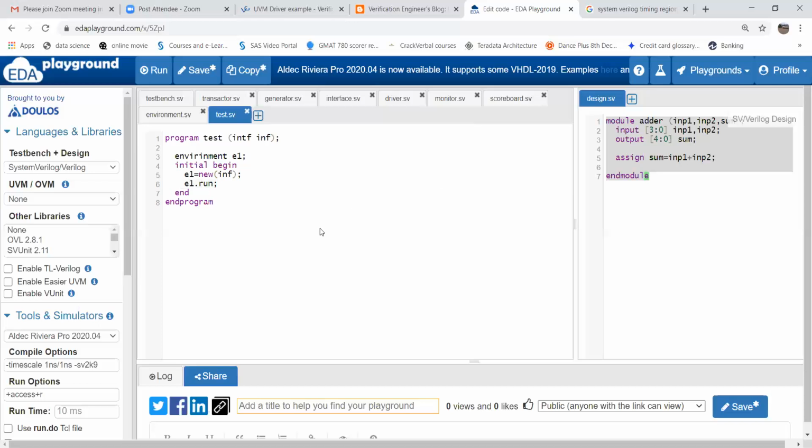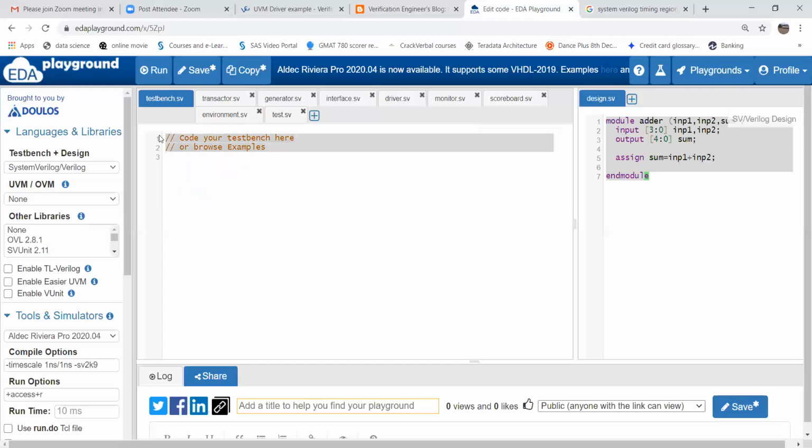So now I should do the instantiation. That is, you can say, top. Top means there I will be just instantiating my test bench and my design. So module top. See, it is not like in one day you will understand. Just practicing. Even this adder code, we first try to understand the code I have written. Then without looking at my code, try to write yourself. Try for mux also, one or two combinational circuits. Once you are acquainted with the flow, then move to sequential circuit.